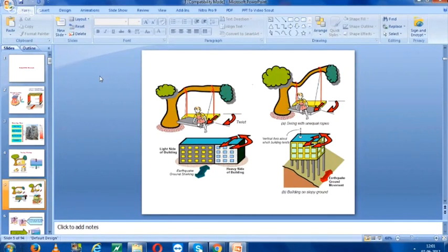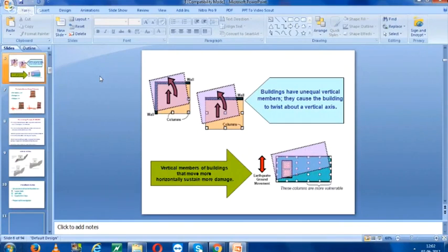Slender columns are going to impart a rotary motion to the structure at the bottom level, and that is going to make the columns critical on the lower side. And in that case, the corner columns are going to be more affected as compared to the interior columns, because they are supposed to transfer the forces to the columns in that parallel line.